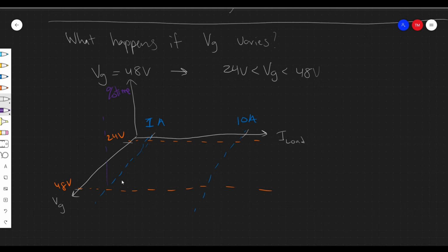And maybe what you end up getting is some kind of heat map telling you how often this converter operates in the different conditions. Maybe it looks something like this, right? So you have some surface, right? And maybe you want to design for the case that you most often encounter, right? Some region where you spend the most time. That's where you might want to optimize your design to operate at its best because you're spending the most time there. And then you just have to ensure that the edge cases are taken care of.